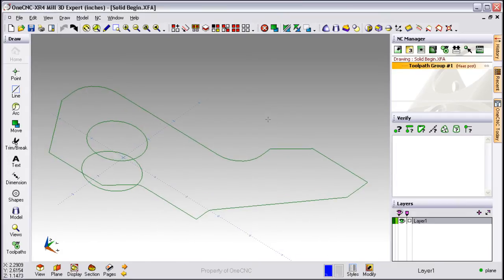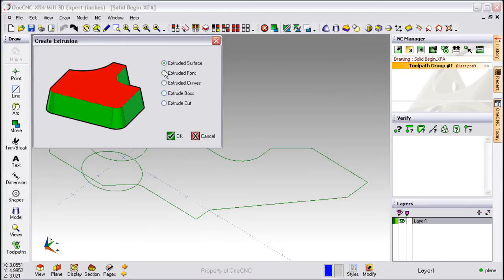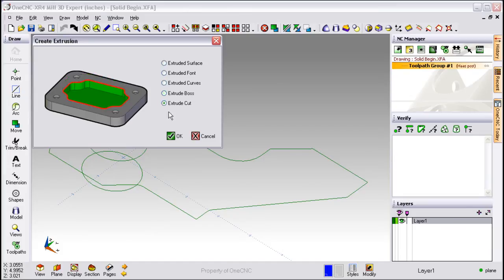If you don't want to use a primitive, no problem. You might want to use our suite of extrude tools. To do that, go back up to the top of the screen and select Extrude. Inside there, you'll find 5 different powerful tools for extrusion.